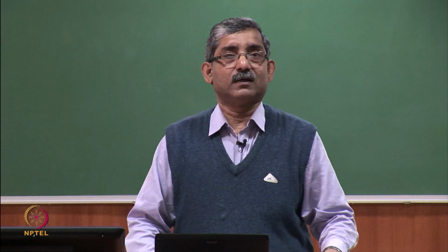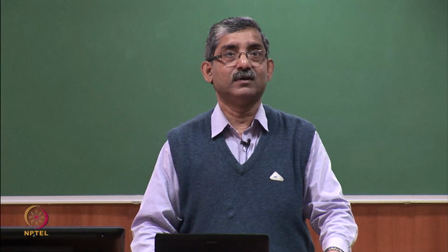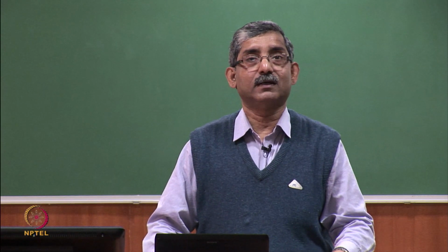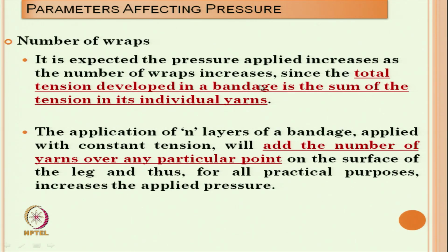Next, the parameter which affects the pressure is the number of wraps. As we go on increasing the number of wraps, the compression pressure increases. It is expected that the pressure applied increases as the number of wraps increases, since the total tension developed in a bandage is the sum of the tension in individual yarns. So, it will keep on adding as we increase the number of wraps.